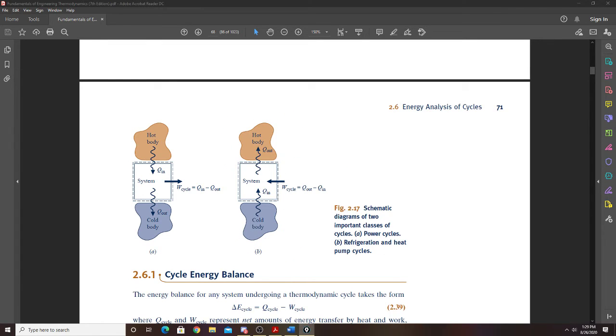How this works in practice is that, depending on what time of year it is, like let's say you're using it to cool your house, there's a reversing valve. What that does is change the direction of the cycle. So essentially you get either this or this, depending on the time of year. You get a different result depending on how you flip your cycle.